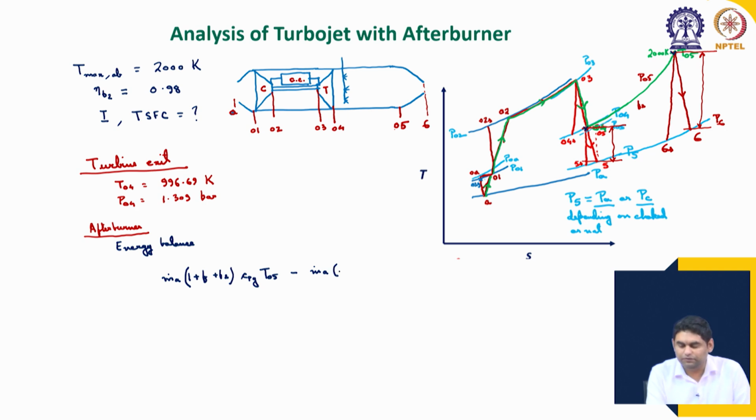At the inlet the mass flow rate is m dot A times 1 plus F. Still remember 1 plus F is there, and the specific heat here is CPG, not CPA, because these are already the combustion products, and we are assuming that although the composition changes, the combustion products have the same Cp as an approximation for simplifying the calculation. Otherwise, the calculation becomes very complicated.